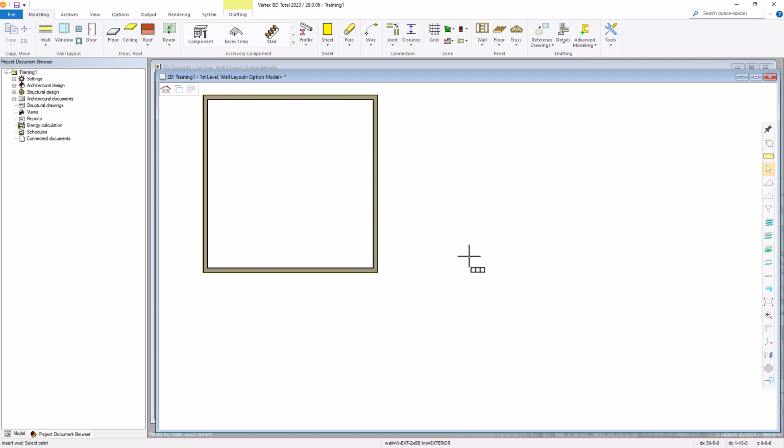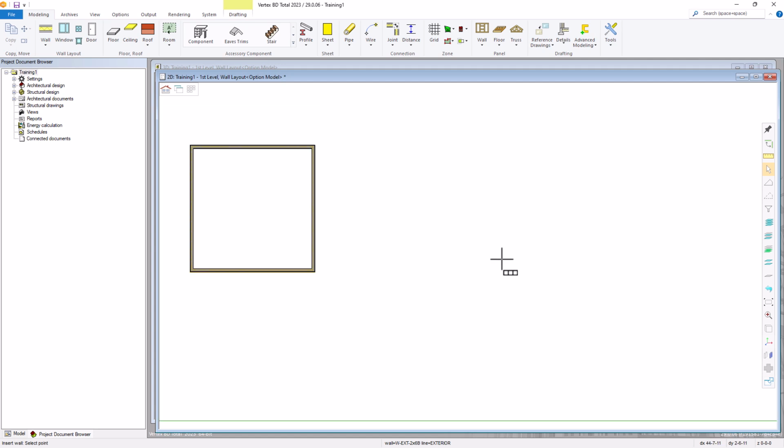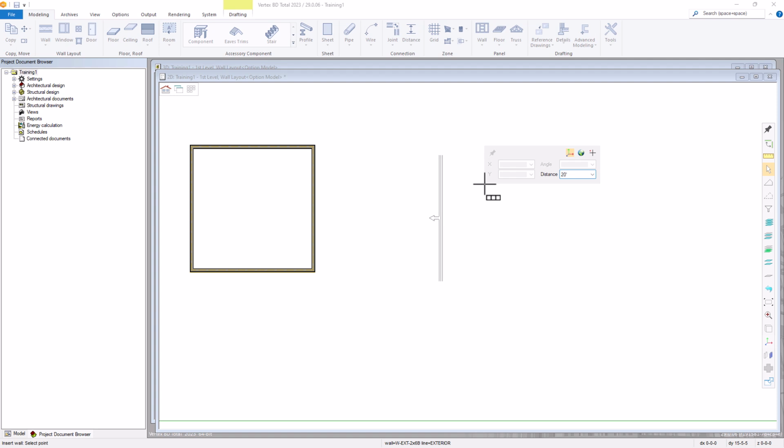Zoom over and do the exact same thing, but this time let's use our constraints. So I'm going to click to begin. Now there's several ways that you can use the constraints. One is visually, like what we have on screen here. So you see the Y, I'll left click, and now I have it locked. And I can type in 20 feet and go in that direction.